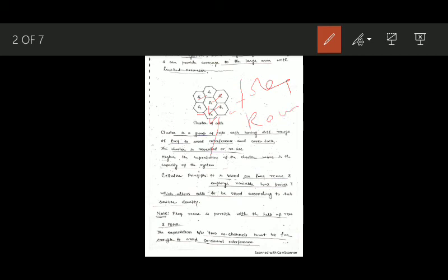So this f7 frequency will be used somewhere near. Suppose a cell is here, nearby this, that cell will be f7. So this again forms a cluster, and this cluster will be repeated again and again over a large geographical area. So f7 will be used by a nearby cluster. This cluster is repeated here, and f7 will be used by this geographical area cluster cell. It is very widely separated, so there is no chance of any interference or crosstalk.